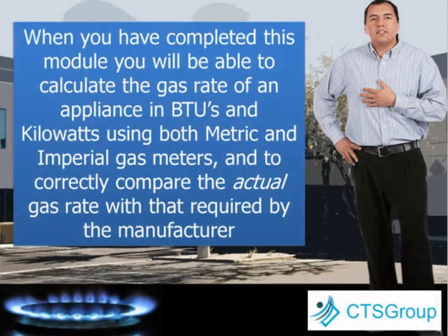When you have completed this module, you'll be able to calculate the gas rate of an appliance in British thermal units and kilowatts using both metric and imperial gas meters, and to correctly compare the actual gas rate with that required by the manufacturer.